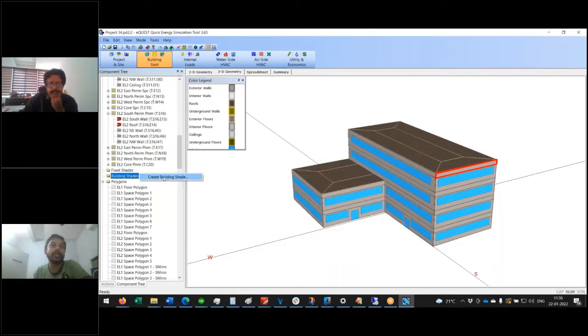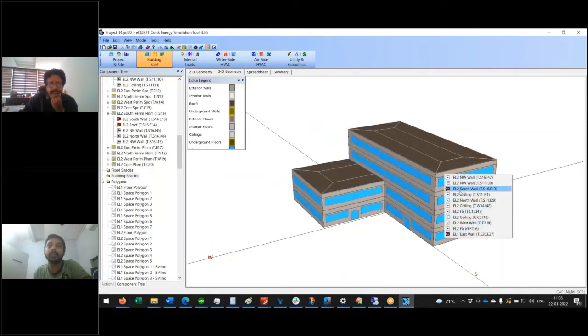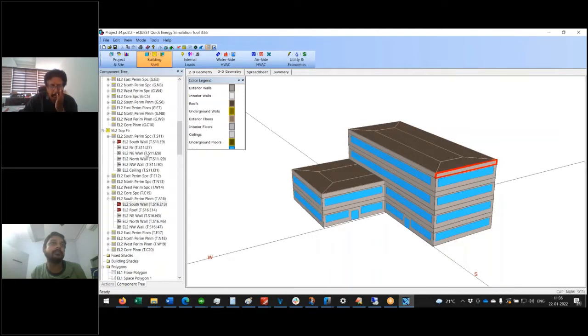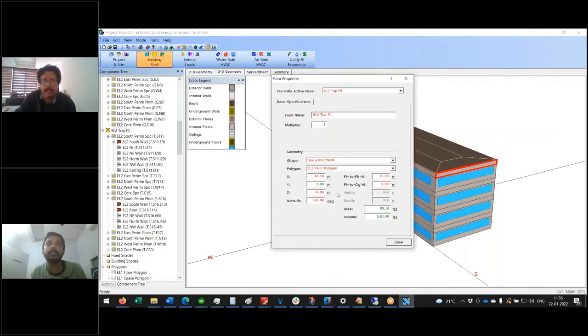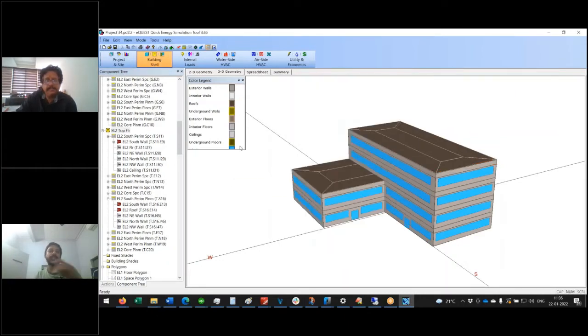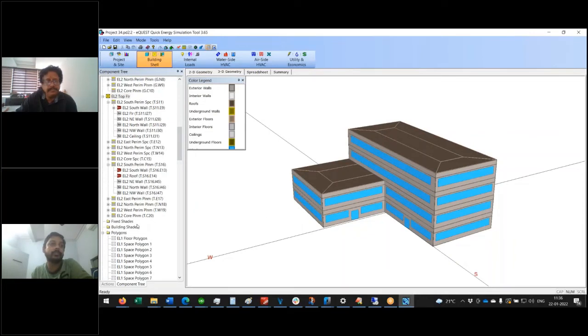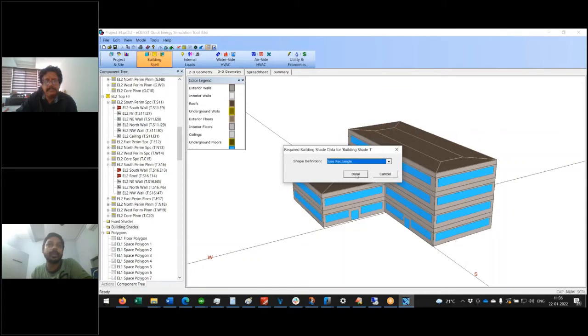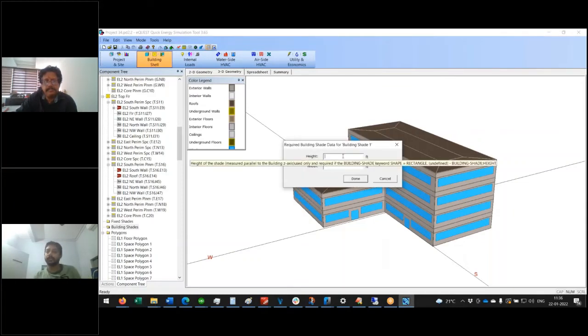So let's go ahead and create a building shade. And of course, the height where it is located, oops, sorry, height is 3. Okay, so 48.1 plus 12 is 60.1. So at a height of 60.1, I'll create a building shade, use rectangle, height I'll say, let's say 5 feet parapet wall, width we had 48.2, I think, if I remember. Yep.